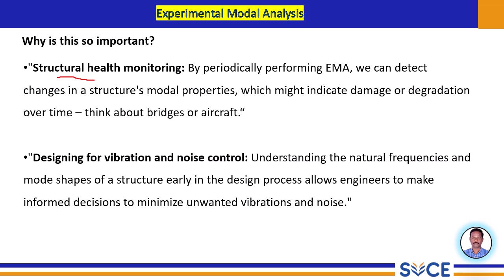The fundamental principle here is that the modal properties of the structure, natural frequencies, damping ratios, and mode shapes, are inherently linked to its physical condition. If any damage occurs, it alters the stiffness, mass distribution, or damping characteristics of the structure, and these changes will be reflected in its modal properties.